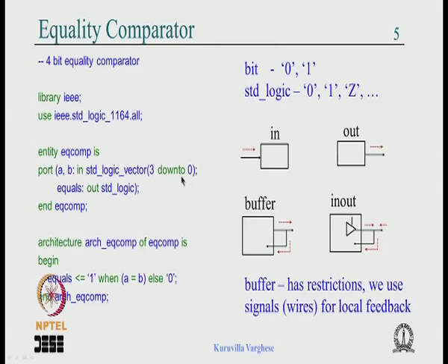Now you might ask what is the big deal, what does it matter, okay. It matters if you have studied the processors from Intel. Actually this has some history behind. The Intel processors used to treat, suppose you have a 16-bit data bus, D15 as the most significant bit, and D0 as the least significant bit, and this was called little endian.